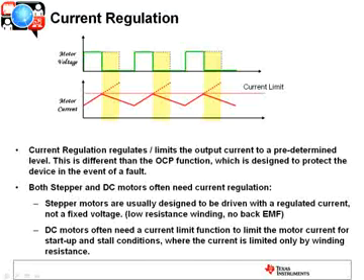And that's what you're seeing in the yellow, where if that had no current limit protection, the PWM cycle would be longer and the output current would be quite a bit higher. But with the current limit in place, it immediately limits the duty cycle, therefore limits the voltage, therefore limits the current. Now this is different than your overcurrent protection, where the overcurrent protection uses a different mechanism, shuts the device down and protects it. This is just to limit the maximum output current.